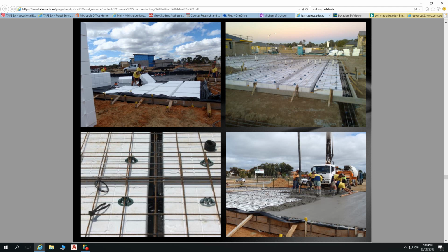It's a lot of work to make this fella's job easier. This guy here, he's got a little box there operating the concrete pump, has to ensure that concrete is placed well, so there's not much screeding that has to happen. I don't see anybody there, and also these guys are on their concrete rakes as well. So it's not a rake with fingers, but it's like a flat plate type thing that you can scoop the concrete around with.